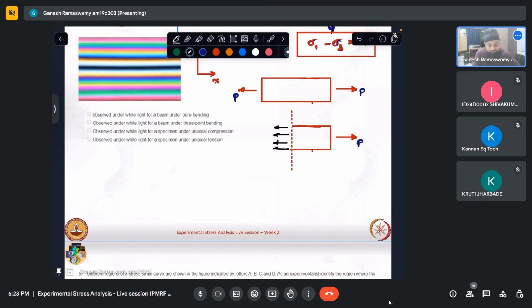And I know since it is in uniaxial tension, when I'm sufficiently far away from the loading points, the stress that gets mobilized, sigma, is nothing but P by A, where A is my area of cross section of that member. When out of plane thickness is not covered, it is just the depth of the member. So far so good. This much we know. I know that this is the state of stress at all the points along this cut.